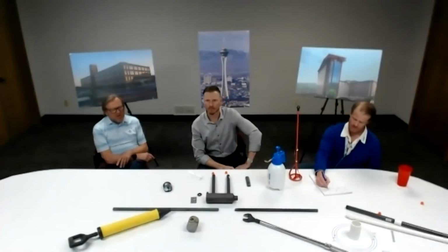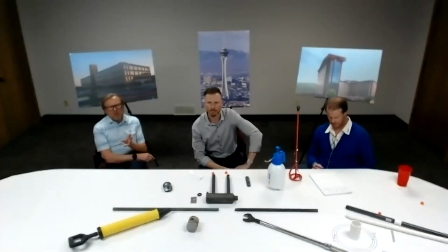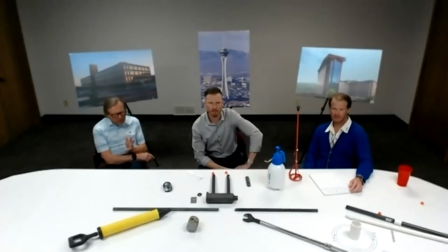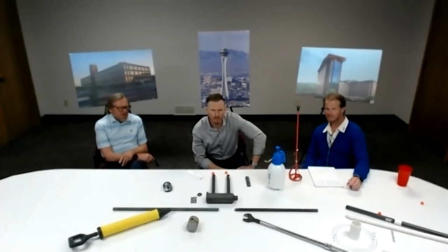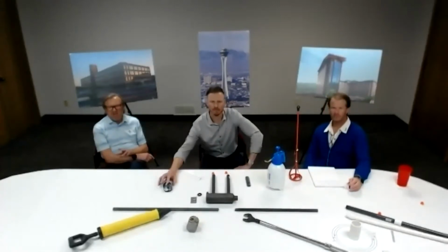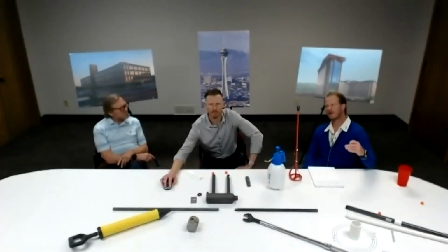We like it because we tested them at 8,000 PSI with Jenny in Chicago a little over a year ago, but it ultimately will reach 12 to 15,000 PSI, so the 8 was conservative. We are testing other grouts right now in our lab in the basement. I don't know how many buckets of cubes we have to go get broken.